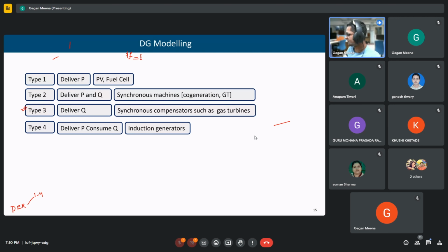The storage of energy, the conversion between electrical and magnetic energy, is possible because of the reactive power component. The actual work which is done is because of the active power. So if the conversion process takes more reactive power, it is not a good conversion process. We want Q to be less and we want more active power output.